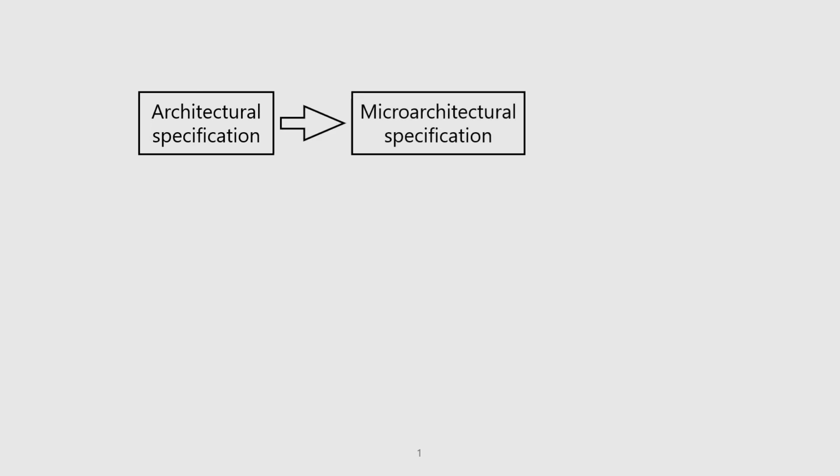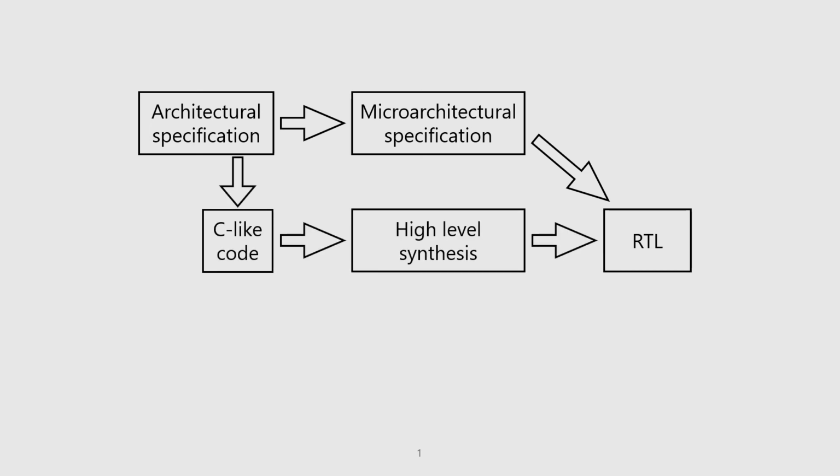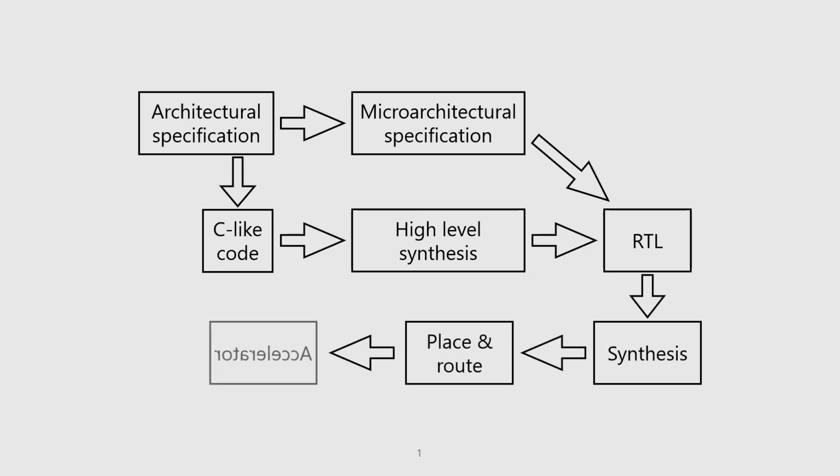When designing an FPGA accelerator, a team generally starts with a block diagram. Then they refine it to a clearly defined microarchitecture. Wait, we're supposed to do that? Okay, after that step, which we definitely all do, we start coding. You could also take the HLS route, which ends up resulting in RTL as well. Then we pass it off to the tool, which synthesizes it, places and routes it, and then out pops your